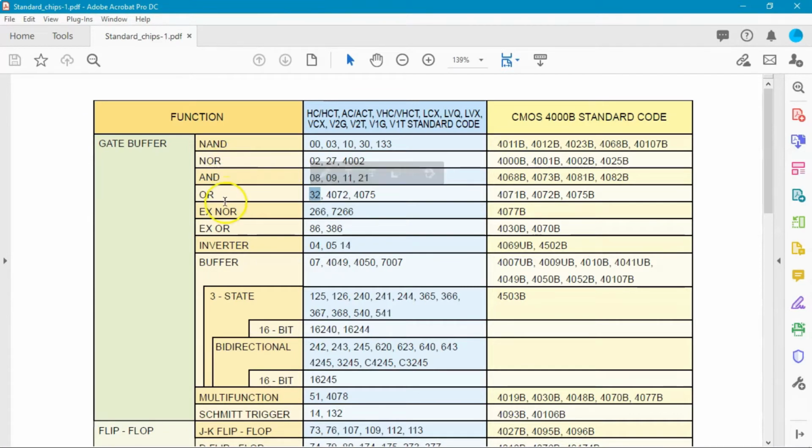The same if you are looking to find some ANDs for the products. You see the 08 and the 11 are going to be right for you if you keep using the 74LS family. You can do the circuit using CMOS families or other families, but if you keep using the 74LS, the advantage is that you have all the models here, so that is okay.